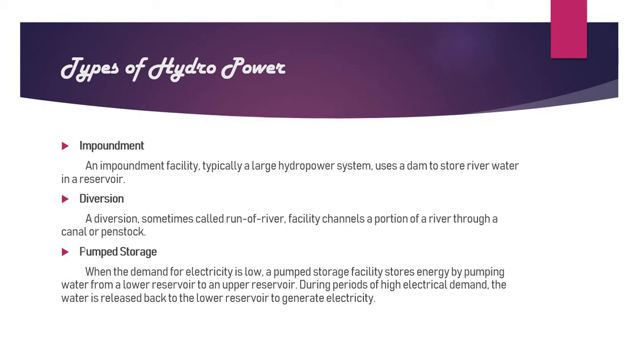The third is the pump storage. When the demand for electricity is low, a pump storage facility stores energy by pumping water from a lower reservoir to an upper reservoir. During periods of high electrical demand, the water is released back to the lower reservoir to generate electricity.